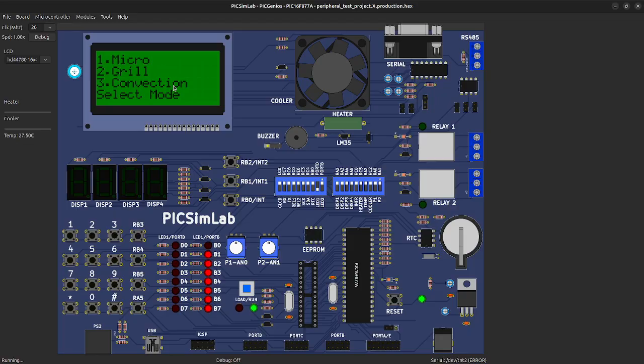In the micro mode, first we give the number 1, and it displays the power, 900 watts. After that we need to give the timer. I'm giving just 0, 0, 1, 0, 10 seconds, and pressing enter hash. It shows the time is 10 seconds. Start, pause, stop: when I start, the fan starts spinning. You can see. And if I press 5, it pauses. The project is paused. Then if I press 4 again, it resumes.